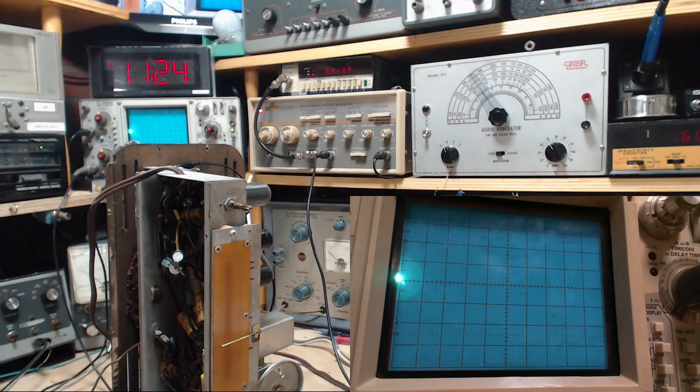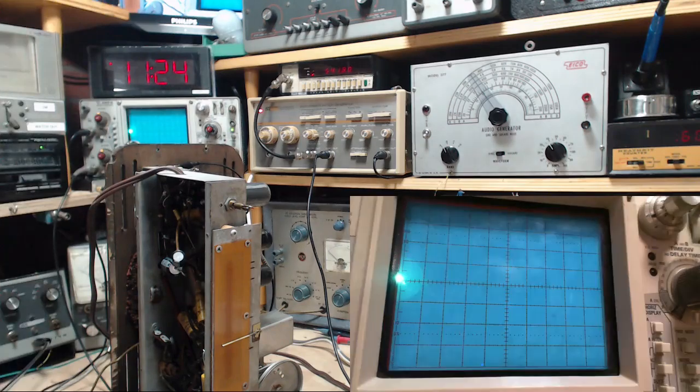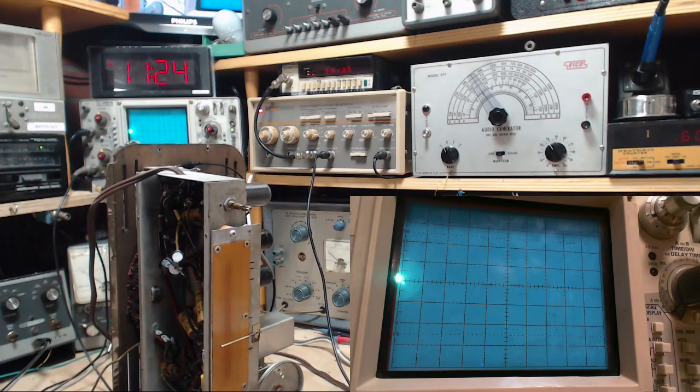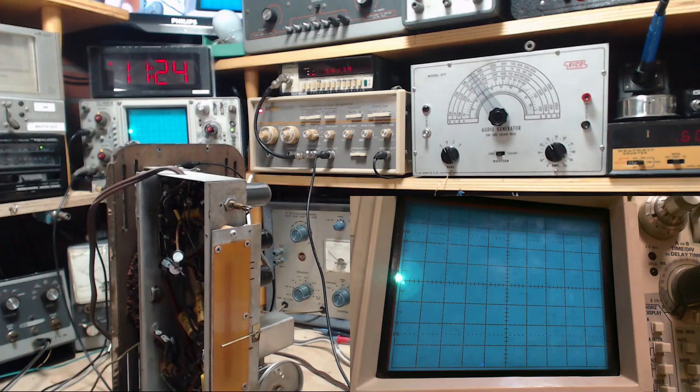The reason it's moving is because the signal on the scope is triggered at a different point in the sweep. So with the radio tuned here, the sweep has to get all the way across the screen before it encounters the tuning point, and then it produces the curve. Yeah, okay, everything is normal. Good. It doesn't indicate the frequency that's coming out of the IF. That's always the same, 455 kilohertz. Mostly snuffed out at the point where I'm looking at it with the scope. The high frequency is mostly snuffed out, leaving just the DC component.